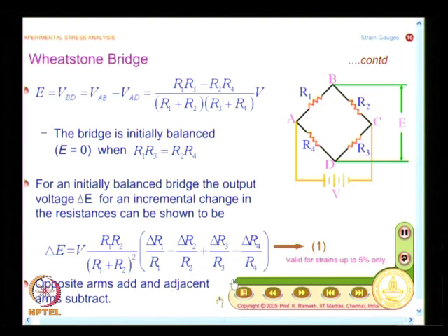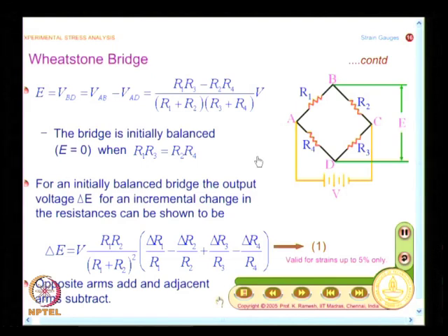from solid mechanics point of view, and if you want to maximize, I can make this minus to positive if I have opposite strains on adjacent arms. I can make this quantity equal to 4. That way I will amplify my signal. The idea is you are measuring a very small quantity and we should always look for ways to increase the signal output. This is also one of the requirements, particularly in transducer design, they would have this bridge factor as 4. So, now we look at the performance of the bridge.